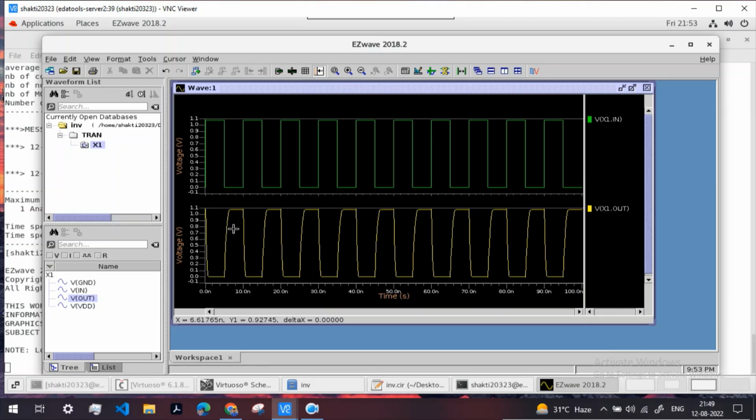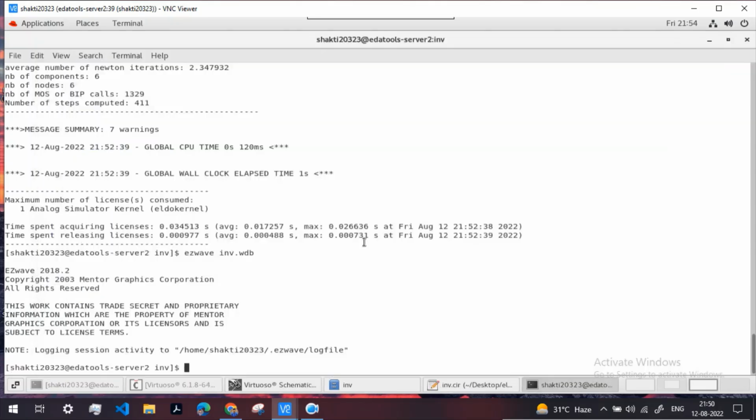So this is the first rising edge, this is the first falling edge, this is the second falling edge. And similarly, this is the first rising edge of the output, this is the second rising edge of the output. And to calculate the propagation delay, suppose we are calculating the rise propagation delay, you can see that we are calculating it at a first rise of output, and here the input was falling. So the distance from this 50% of input to this 50% of output when it is rising is termed as rise delay. So this was all about plotting the transient simulations on ELDO.